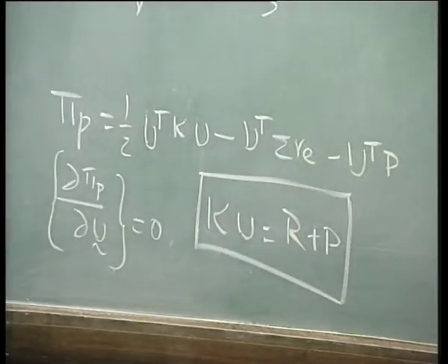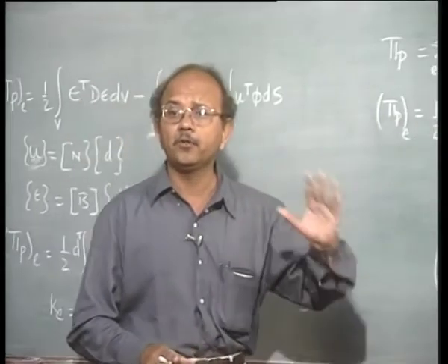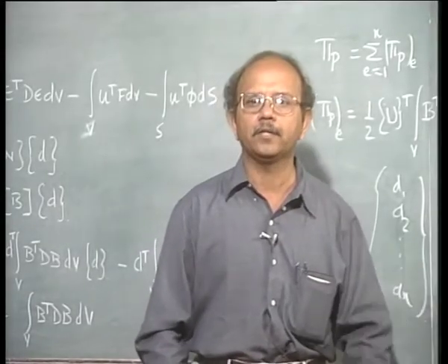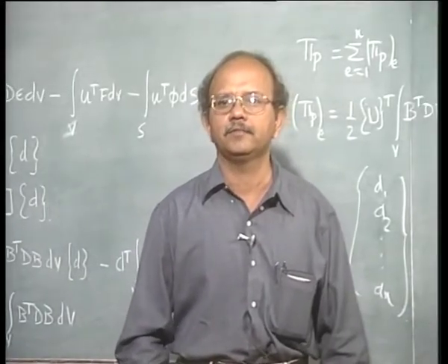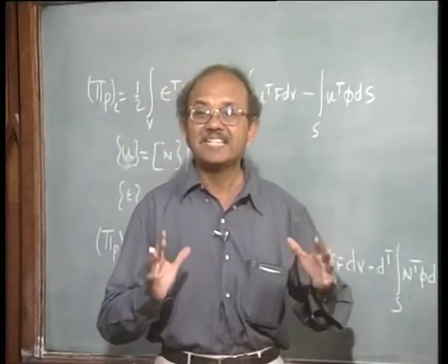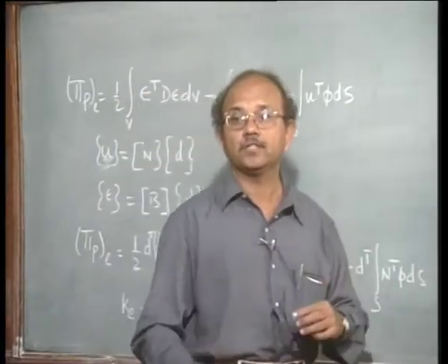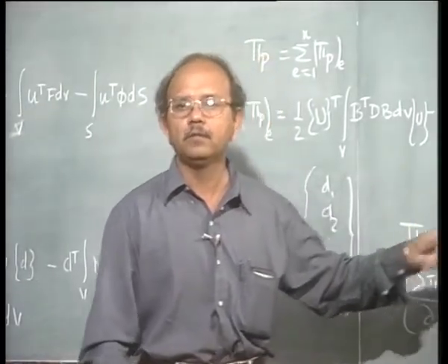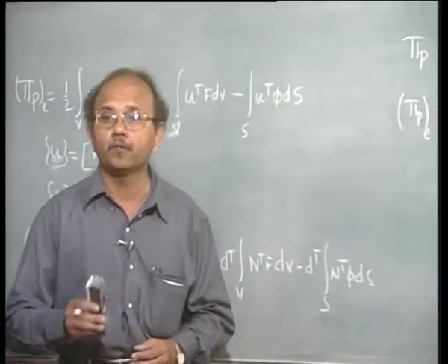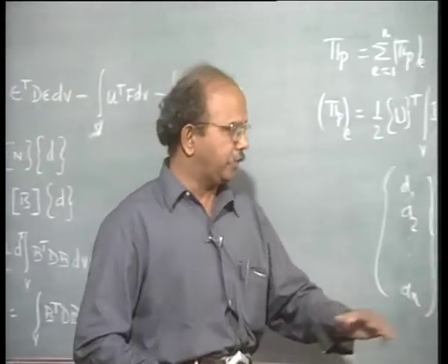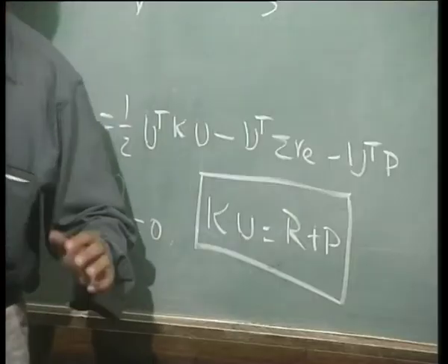Now what is that we have done? We have reduced, ultimately we have reduced a very complicated differential equation into a simple algebraic equation. These forces that we have developed are what are called as consistent nodal forces. Please note, though it was a pressure term, though it was a volume, though the body forces were acting over a volume, all those things were there. Ultimately when I reduce it to this equation, what is it that I have done?